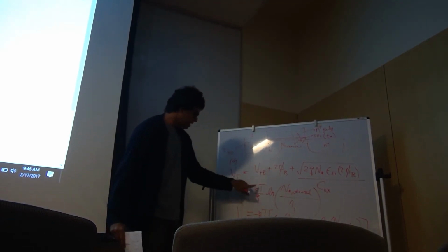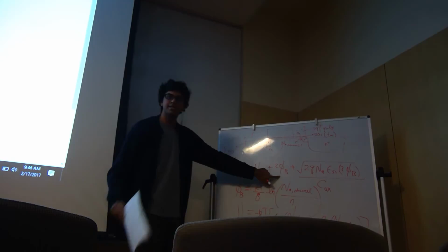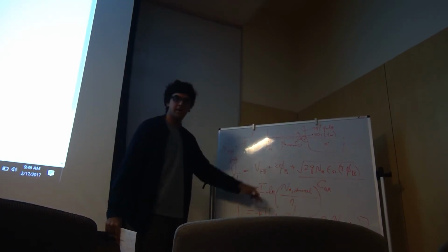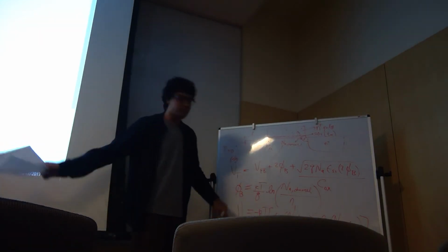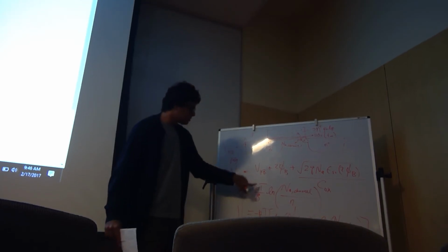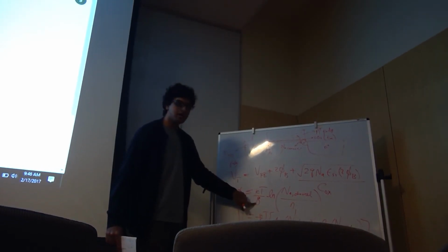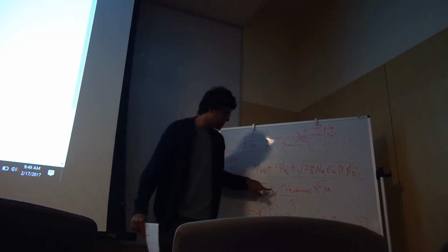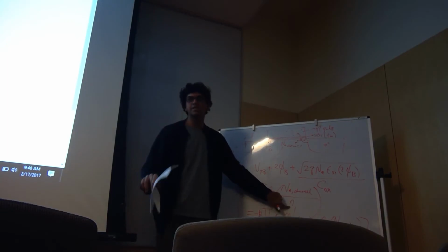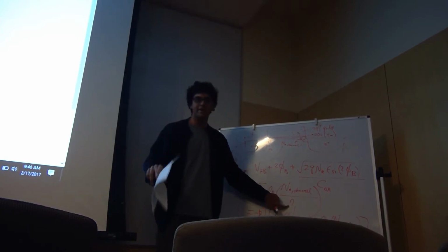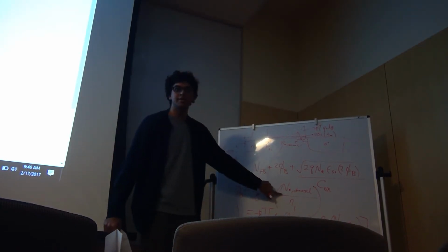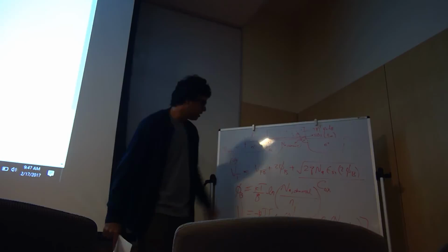So this 2φB is called the surface band bending. Again, this is another transistor equation, okay? So I can go over this if I have time in the end, but for now, just assume this is the equation to solve it. This is the Boltzmann constant, temperature, the charge of an electron, natural logarithm. This is the intrinsic carrier concentration of silicon at room temperature. Just assume room temperature, even though your device gets heated up. Then this is your dopant concentration in the channel. This is the thing you need to actually solve for, okay?